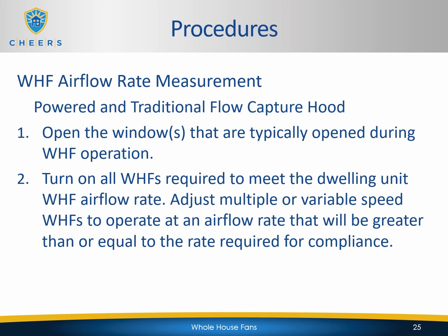Now let's look at the procedure for powered and traditional flow capture hoods. That's going to be the same, even though they function a little bit differently. The process for taking measurements is the same. The setup for the equipment is a little bit different, and again, you'll want to refer to your manufacturer's instructions for the specific type of flow hood that you have, so that you make sure that you set it up correctly for the type of airflow test that you're going to be taking.